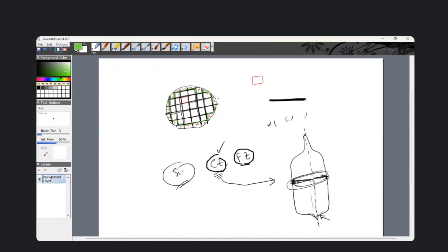But problem is that as it is circular, the disc is circular, so the dies that you have built or realized along the surface, sorry, along the edges, or close to the edge of the wafer, those dies are not perfect in terms of the shape. That means they're not complete. They're incomplete. Suppose this die. The figure looks like this. Incomplete. This is incomplete. This one incomplete. They're not complete in terms of the shape. So that means we cannot take it.